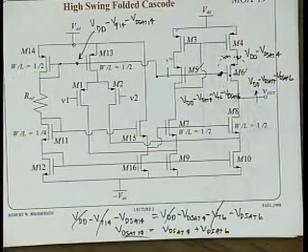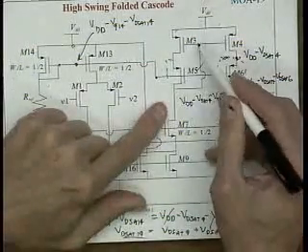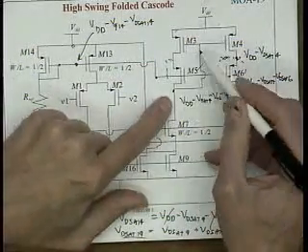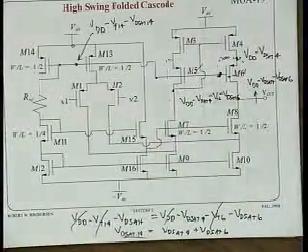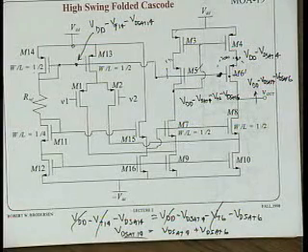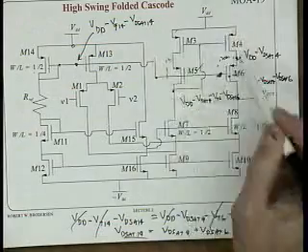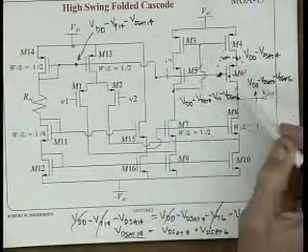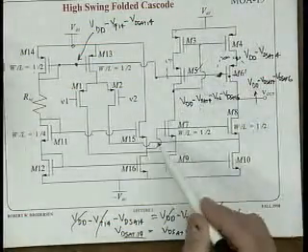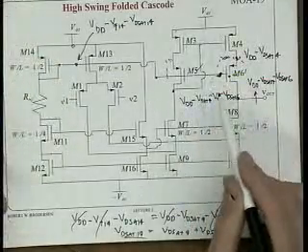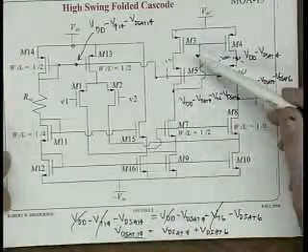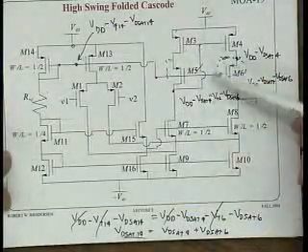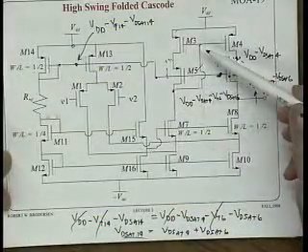Okay. So what's this little bias business going on here? Why do we have this connection? This is kind of a nice little high swing bias circuit. It's a lot nicer than the one we had before. Remember, before, in fact, we have it here, we had that little source follower with the battery and all that kind of thing. So I'm claiming this is also doing high swing, but it's a lot simpler. It's the same number of transistors, no source follower with a little battery, right?